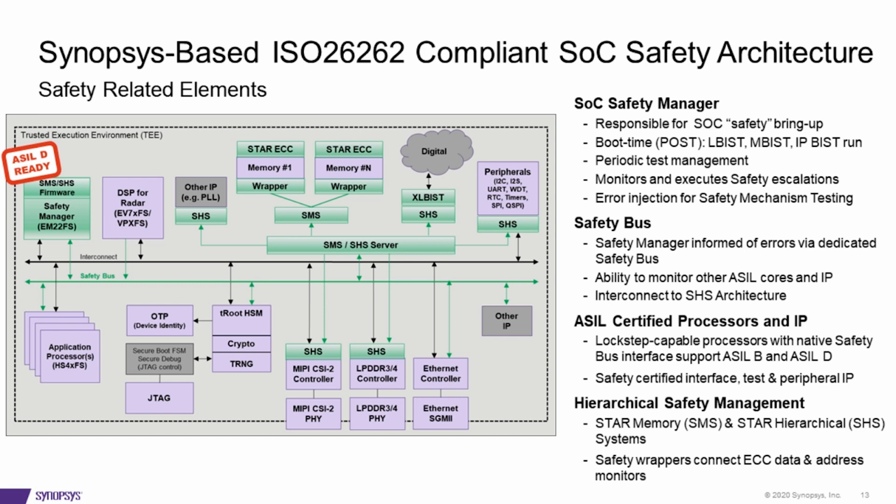Another important aspect of Synopsys' product offering is the tie-in between the safety manager and the logic for memory BIST and logic BIST. Synopsys has a set of products called Star Memory System and Star Hierarchical System that effectively create wrappers so that customers' IP, whether it's Synopsys IP or their own IP, can be tied into the same safe network, if you will, or safety architecture.